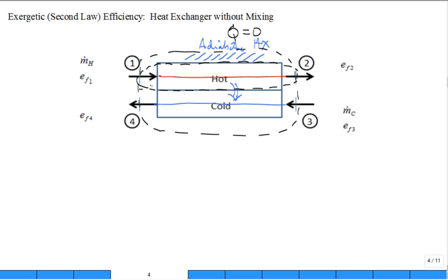That control volume with respect to the hot fluid stream is not adiabatic. There's a heat transfer out of the hot fluid stream, not to the surroundings outside the heat exchanger, but within the heat exchanger to the cold fluid stream. And sometimes we'll do an analysis of a control volume around the cold fluid stream. So when you're doing a heat exchanger analysis, be careful: is it just the hot fluid stream control volume, the cold fluid stream control volume, or both fluid streams and the entire heat exchanger control volume around it?